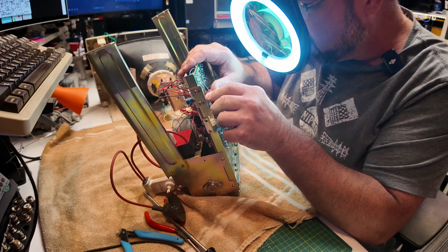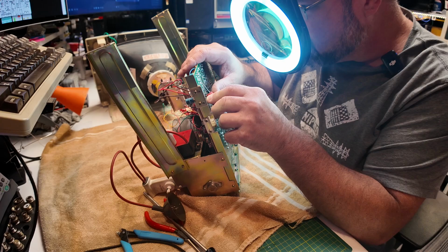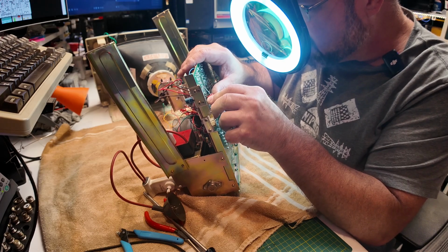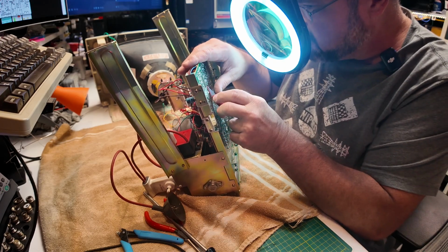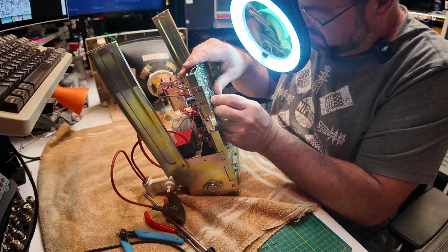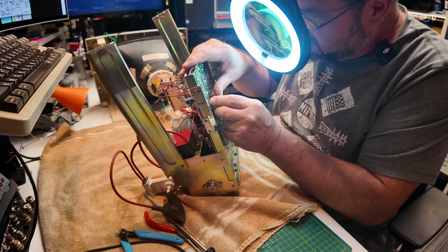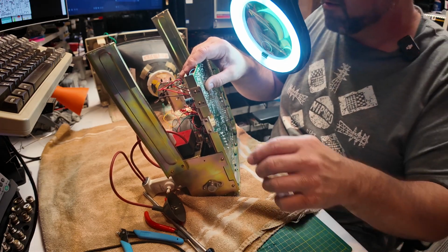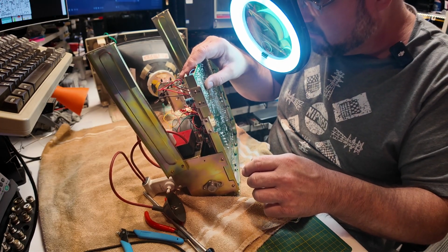And it's all about the manufacturing. When they put this thing together, they bend those pins down in the corners. It helps hold the chip in for them while they solder it. So it does not make our lives easy when the chip burns out and we have to replace it.